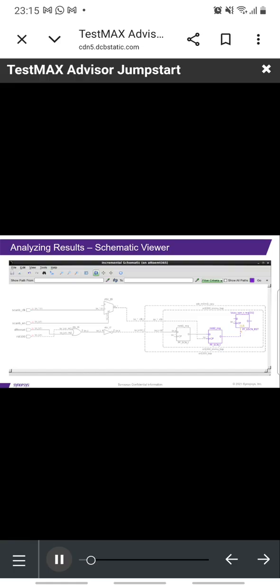This displays the Async 07 violation in the schematic viewer. The violation shows that the reset of the flop on the right is at X and is not set inactive during shift. Please note the various annotations used by the schematic viewer on the nodes to display the values. For example, sh_1 denotes that that particular node is fixed to a constant value 1 in the shift mode, whereas sh_caret means that there is a clock propagating through that node or a clock constraint on that node.